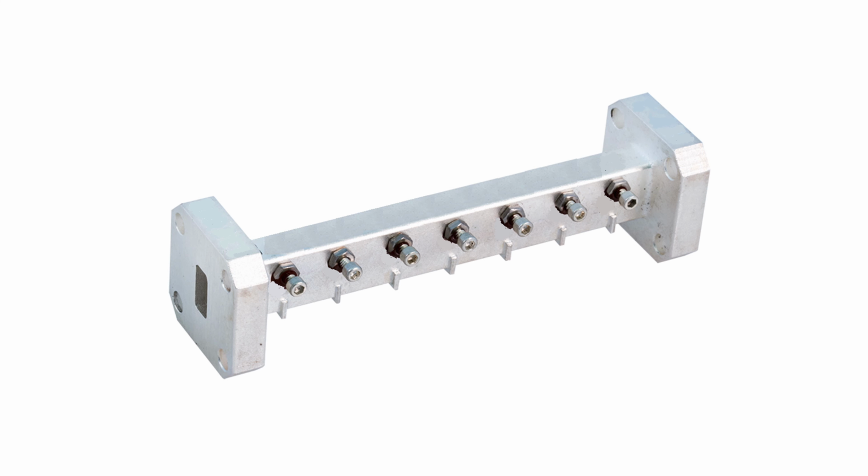The image shows a waveguide bandpass filter used by MPT in one of its recent test and measurement products. Waveguide filters have the distinct advantage of providing low insertion loss and very high rejection slope for undesired signals. The main disadvantage of waveguide filters are their large size and that they weigh quite a bit.